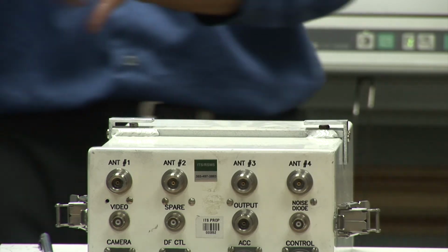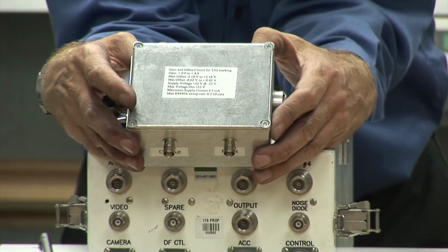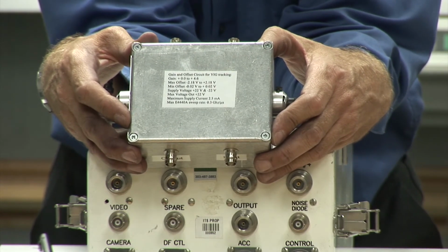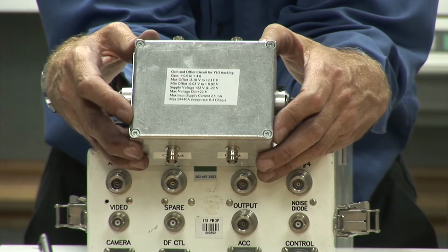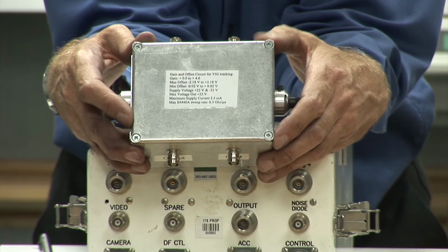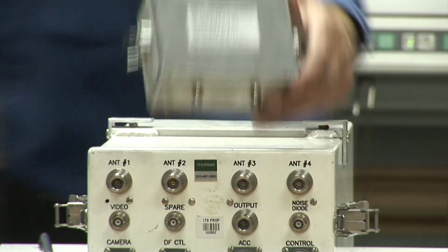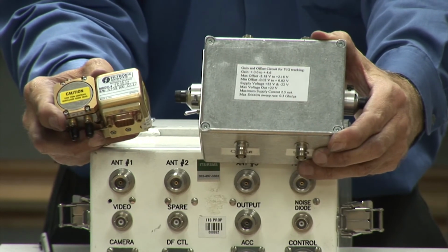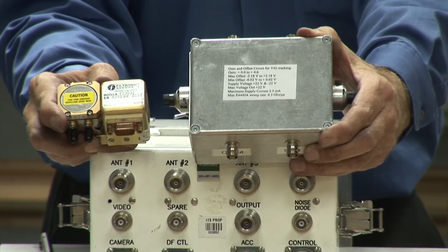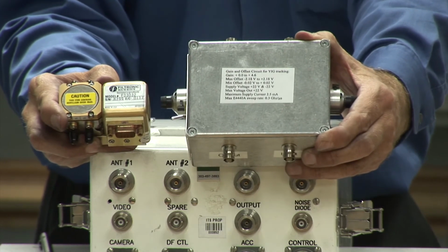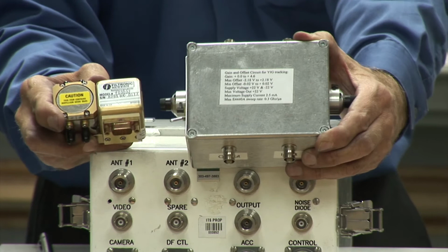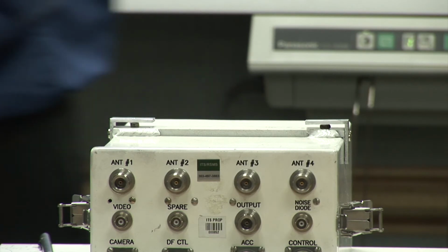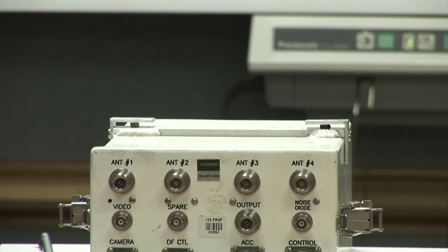Here's something else that's necessary in our measurement systems typically. This is a box which contains a pair of op amps, and this box converts the voltage that comes out of the spectrum analyzer, which is proportional to the spectrum analyzer's tune voltage, to the proper voltage to operate with the YIG. If the YIG happens to have the same voltage requirements as the spectrum analyzer, we're lucky. If we're not lucky, then we use a box like this in the path to convert the analyzer voltage into the right voltages for the YIG. By the way, typical YIG control voltages are something like 1 gigahertz per volt.